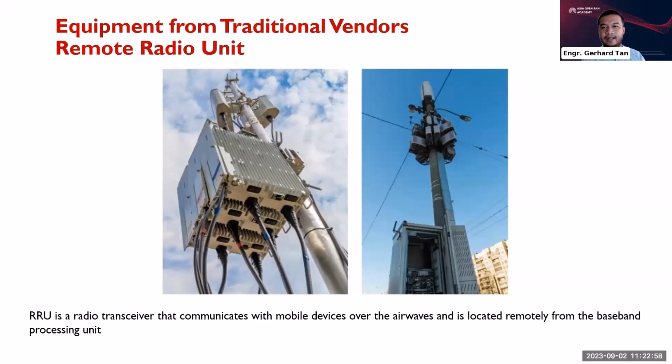And of course, you have your picocell, which is 3 dBi omni and 7 dBi panel. So this one, you can see how it's being deployed for street level connectivity. Of course, you have the power cable going to a commercial power nearby. So don't expect to have redundancy on that, because once there's brownout, that will basically be affected. Unlike the big one, the macro site, it has a generator set, it has an uninterruptible power supply, so it has backup. In principle, if brownout, you still have 8 hours on the go. You still have your signal.